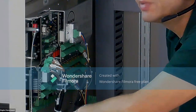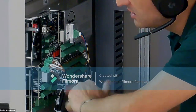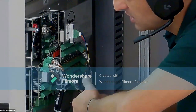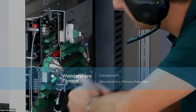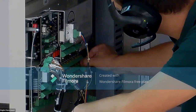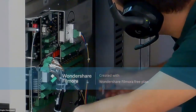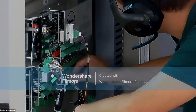Sometimes there can be a mistake, but usually that is found in sea trial or shop test. So unless you are taking over a new vessel, I assume that all the wire tags correspond with the connector numbers. So you remove the plugs one by one from the MPC.